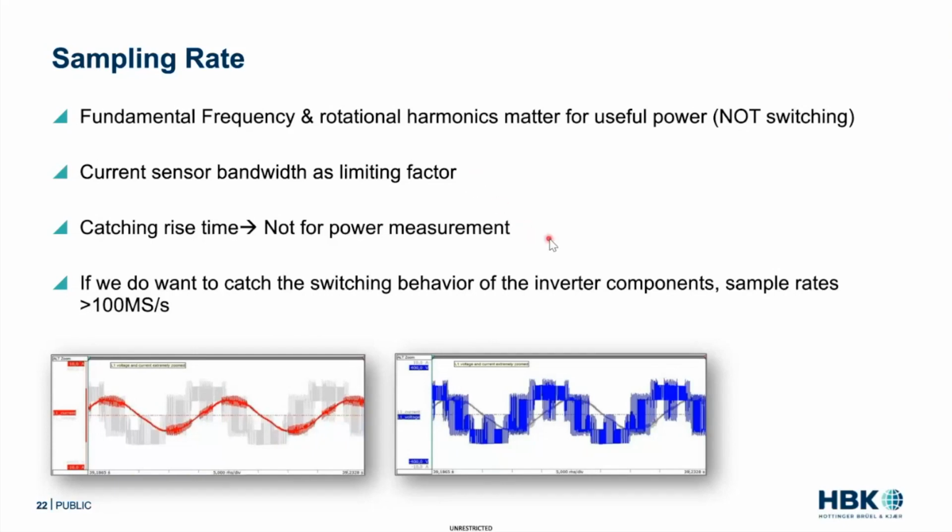So catching the rise time, I get this question a lot. Don't I need to catch the rise time of my switch? Well, there's no power in the switch. You need to know when it turns on, but not really the details of it, because the RMS is in proportion to when the switch turns on over a very, very long period of time. So you don't need to catch the rise time, because that real power is in the fundamental and the harmonics. So for power, you don't really need that.